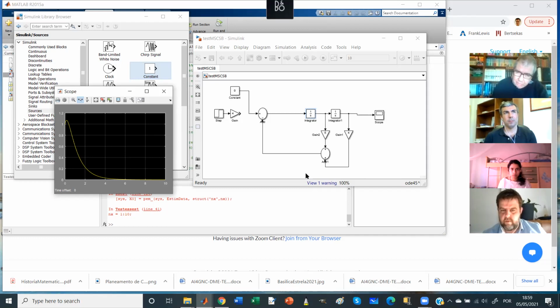There is one value of K for which both poles are real and in the left half plane. And then you have a double pole. There is a value of K, which is K equal to 4, I think, for which you have a double pole, that is to say 2 poles at the same position, at position -1.